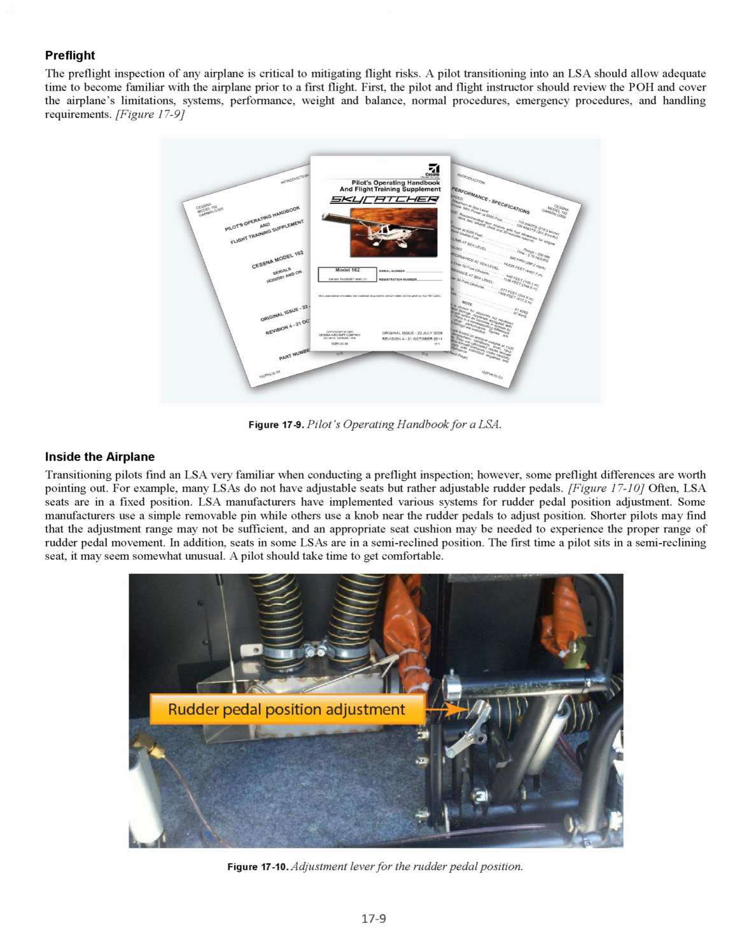Pre-flight. The pre-flight inspection of any airplane is critical to mitigating flight risks. A pilot transitioning into an LSA should allow adequate time to become familiar with the airplane prior to a first flight. First, the pilot and flight instructor should review the POH and cover the airplane's limitations, systems, performance, weight and balance, normal procedures, emergency procedures, and handling requirements. Inside the airplane, transitioning pilots find an LSA very familiar when conducting a pre-flight inspection. However, some pre-flight differences are worth pointing out.